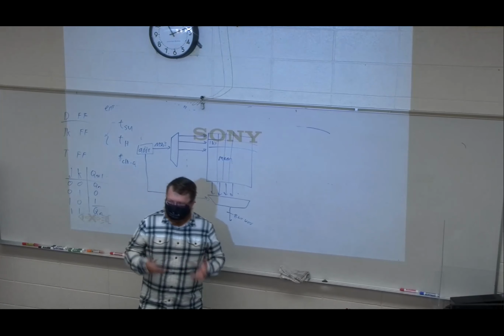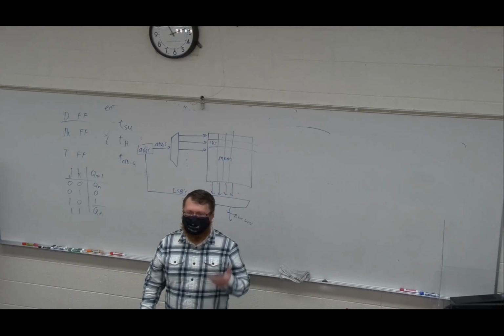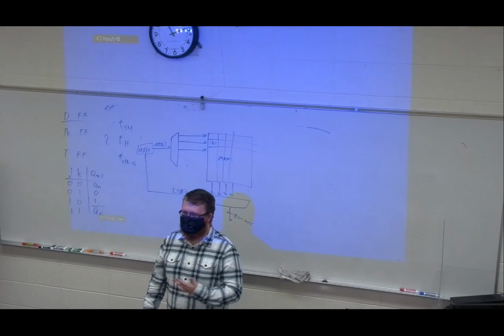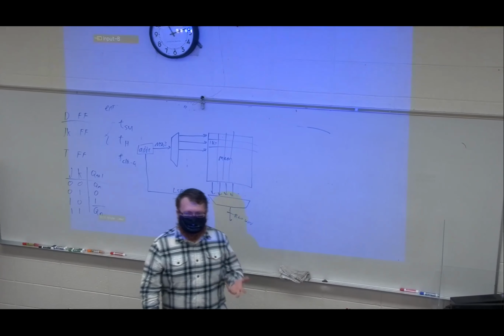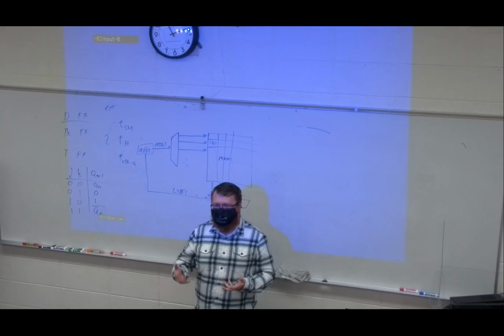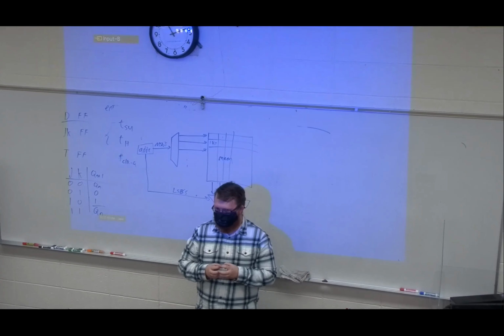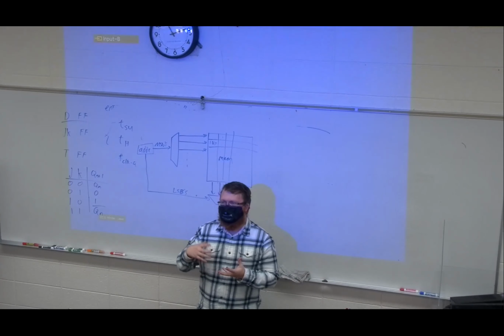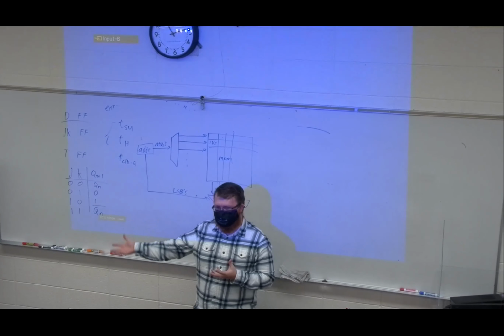So we're not writing a standard programming language when we're writing VHDL. We're writing a hardware description language. We're using code to describe what hardware is. Synthesis and implementation are the process of taking that code and first turning it into logic, which is what synthesis is, turning it into the circuits. And then implementation is specifying it for your target.